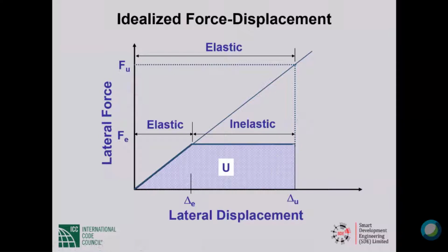The inelastic displacement cannot be such that our structure will collapse on us. So we should not set the design strength level so low that the resulting inelastic displacement exceeds what we call the inelastic deformation capacity of the structure, the capacity of the structure to withstand inelastic displacements while still carrying factored gravity loads.